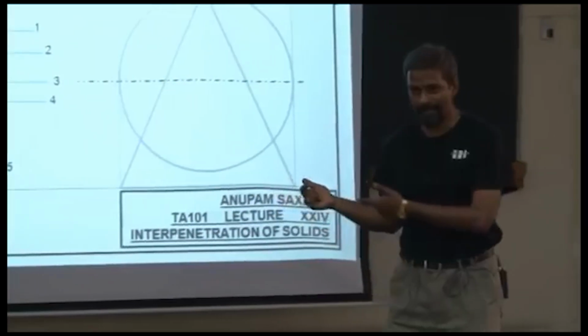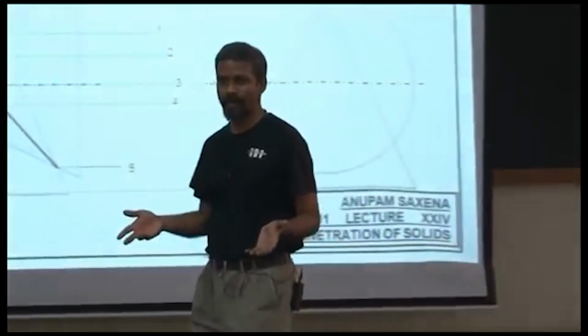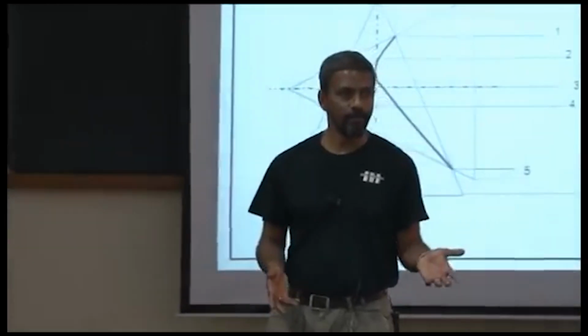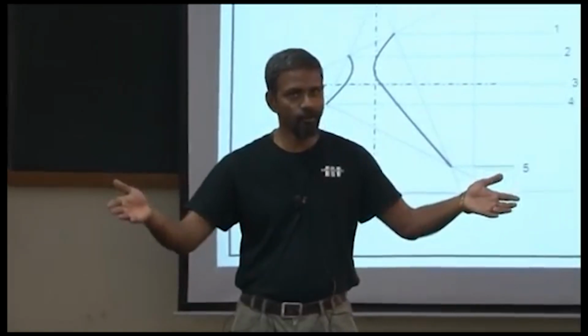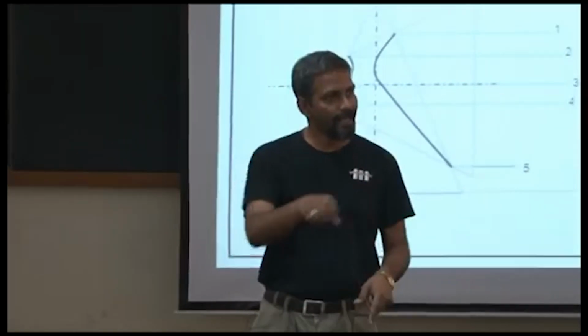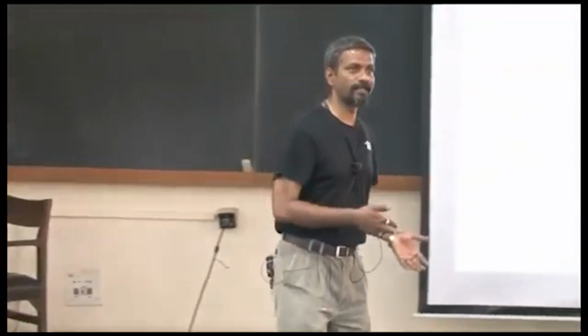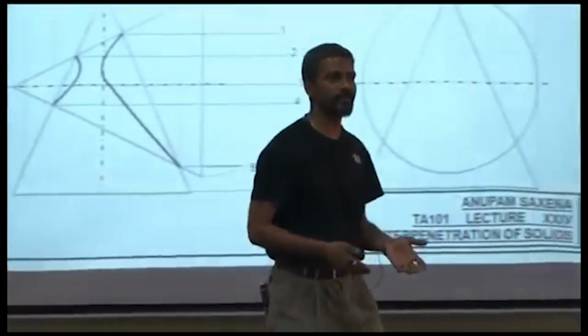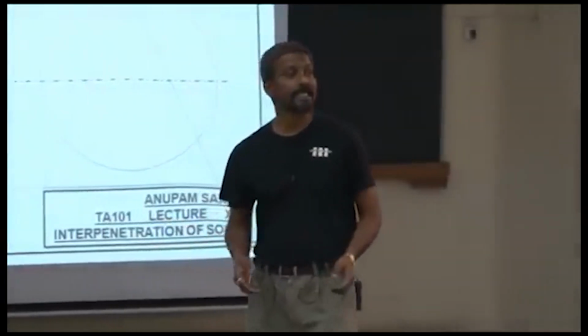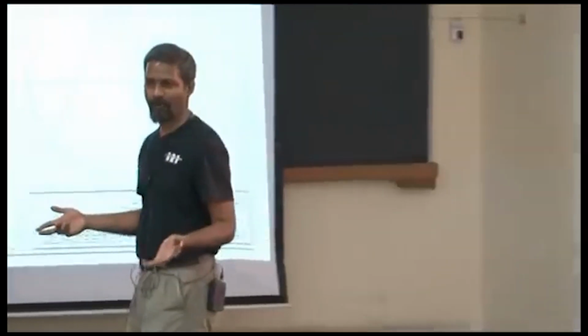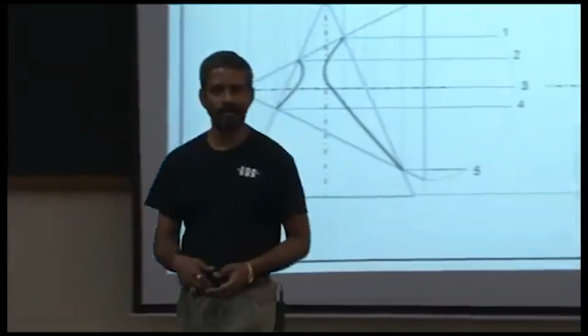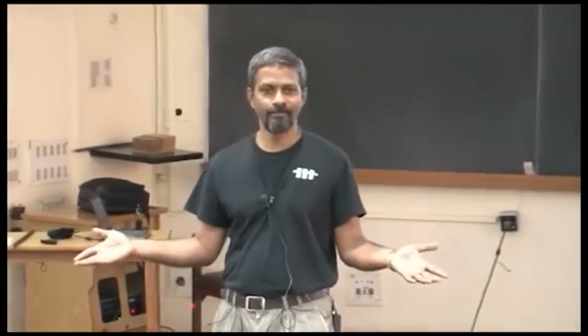In fact, in the example on Tuesday, both the solids are developable. Okay, use the fact that the cone is developable, cut the cone, spread it out. You already have the intersection contour in there. Cut that part out. Flap or fold your cone back into shape, and then you have the slot. So the first part, intersection, is something that has been covered today and last Tuesday. Development will involve 2 more lectures next week, and then you will learn how to cut one solid to be able to precisely fit the other one.